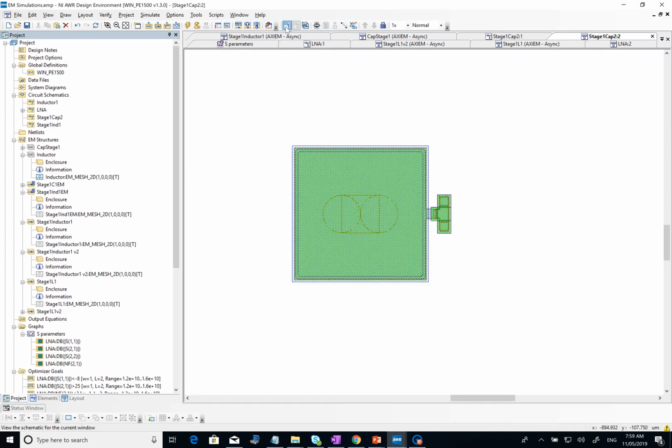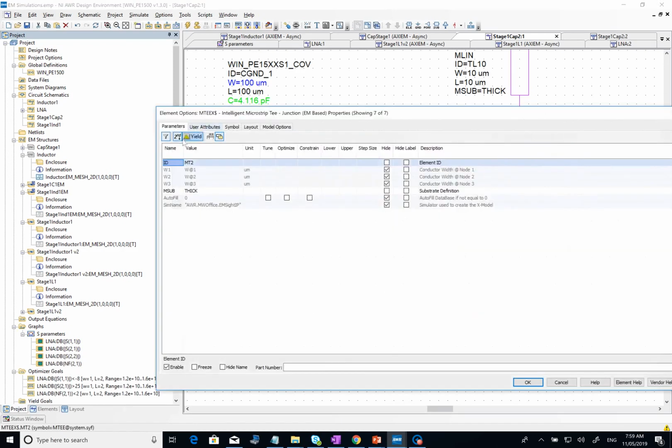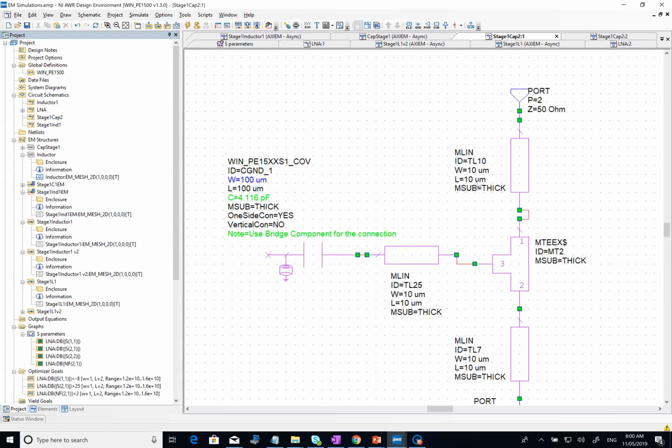When I did it with width at 1, what I did was go into properties, go into second, and then instead of W1 I say width at 1, so it looks at the connecting port at port 1 and takes that width in. It can only do that if this element is intelligent enough to provide that width to here. Now that's why you had issues in your simulations earlier.